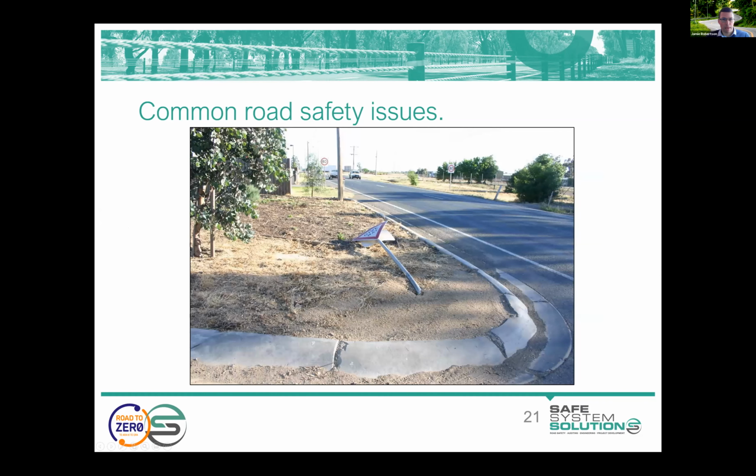Roadside furniture impacts is another telltale sign, which in itself perhaps isn't a big issue, we can go back and replace or reinstall the sign. You need to be thinking about what drivers might do alternatively to avoid striking these signs. Another prime example is a keep left sign on a splitter island. You frequently see these signs knocked down.